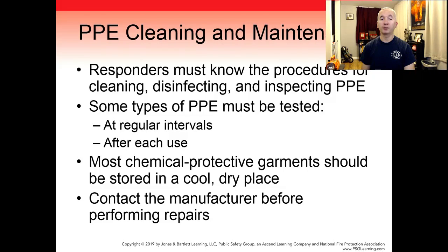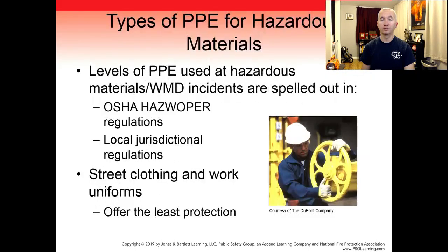Responders must be aware of the procedures for cleaning, disinfecting, and inspecting PPE. Some types of PPE are required to be tested at regular intervals and after each use. For reusable garments, individual manufacturers have well-defined procedures for maintenance, testing, and inspecting their equipment. Most types of chemical protective garments should be stored in a cool, dry place. Contact the manufacturer before performing any repairs as well.